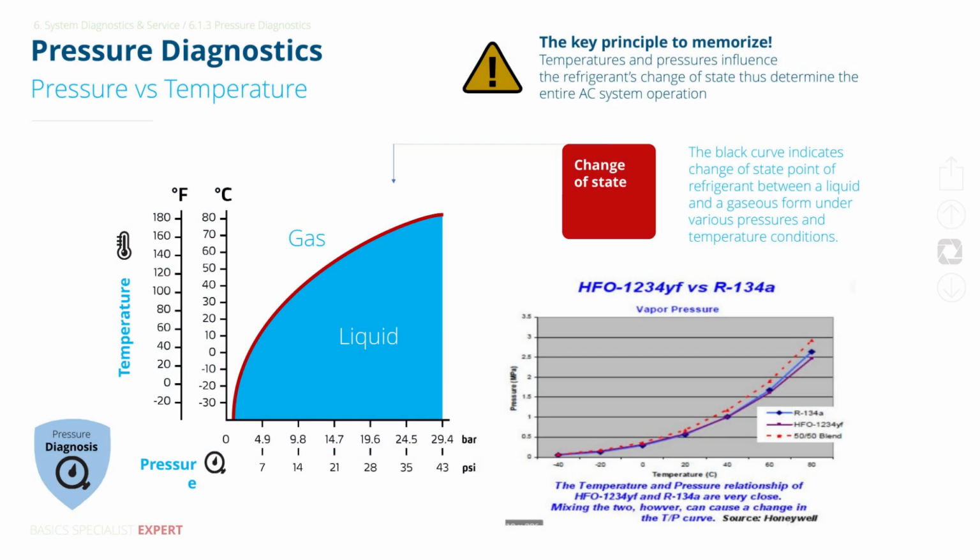An AC system depends on both high and low pressures and temperatures to keep the loop moving. Since pressure and temperature rise and fall together, the refrigerant changes state at its saturation point. The high side releases heat and builds pressure, while the low side drops pressure so the refrigerant can absorb heat before returning to the compressor.